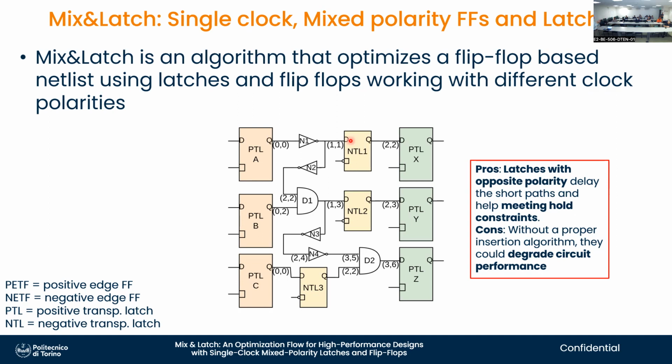you combine these techniques. The negative latches are a big gun. You can use them to have a big increase in the delay of this signal with a relatively small amount of area. Inverters, routing, clock skew, adaptive clock skew is a smaller gun, much more precise, which can be used for the final tuning, and we exploit those. Okay?